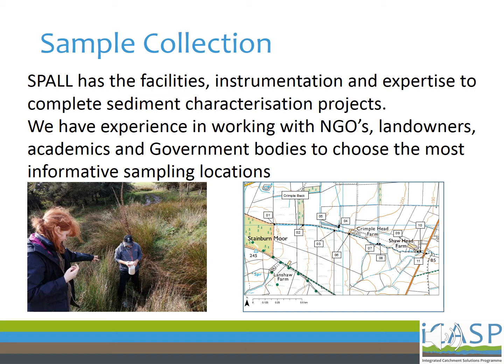As Janet mentioned, not all input types are on SciMap, and as rainfall is done as an average, some high flow events may be lost if just SciMap is used. By working with landowners and other organisations, we can get a true picture of the catchment and the best sampling locations and any high flow events which would otherwise have been missed. This reduces the number of samples required to gain an overview of the catchment while retaining the resolution of the results.